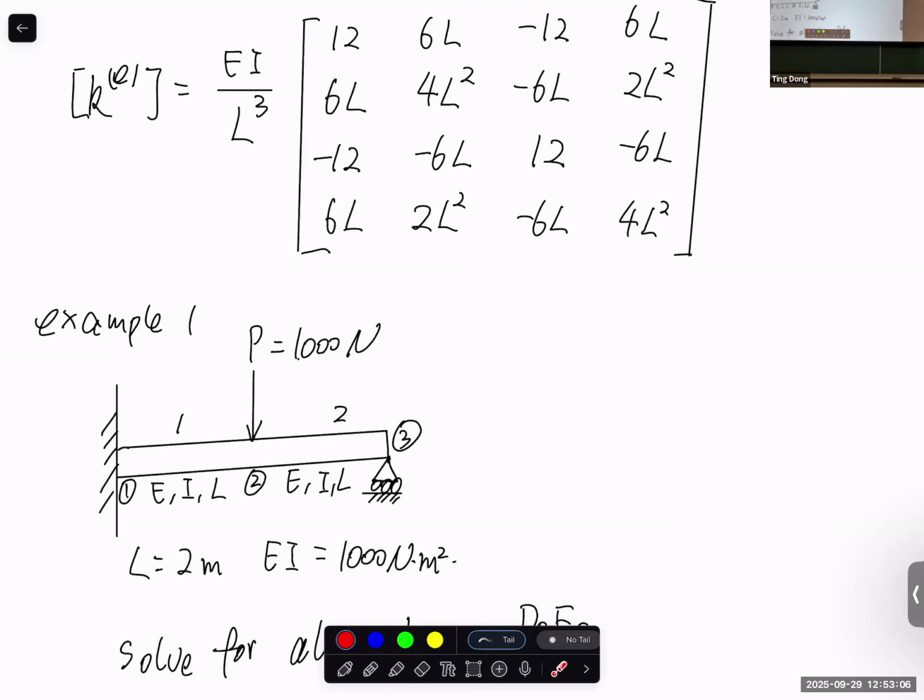Since many of you are from the aerospace program, another situation is that, let's say, you have the wing. And for one side of the wing, you can consider it a kind of beam. Basically, the connecting point of the wing to the fuselage is more like a clamp situation. It fixes the deflection, it fixes the rotation at the root of the wing. And for the rest, the other side is a free end. And if the wing is designed well, you should expect an elliptical distribution of lift. Again, it's not like a concentrated force applied at the wingtip, but an elliptical distribution of lift on the wing.